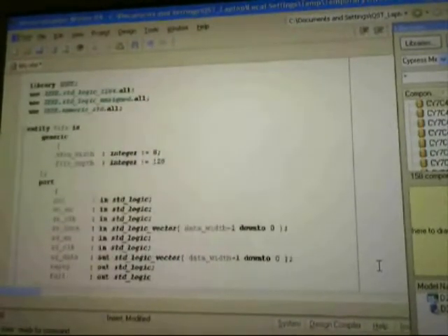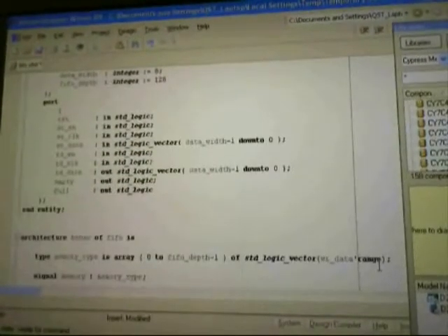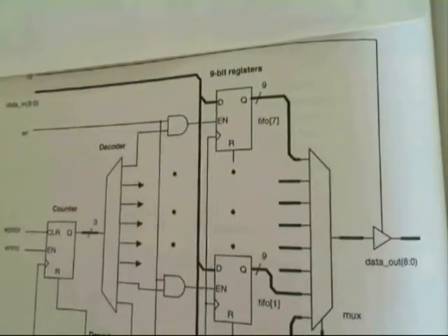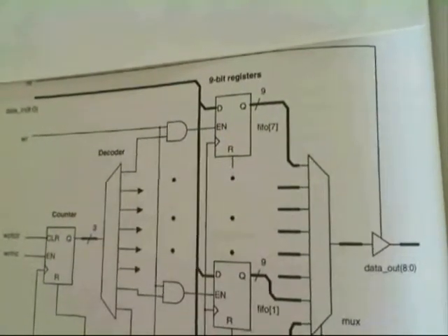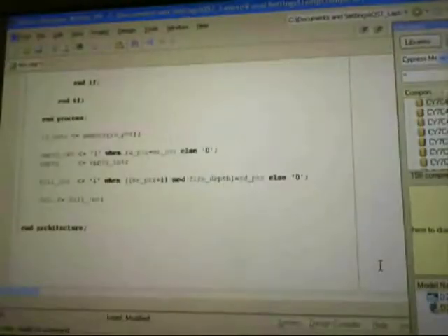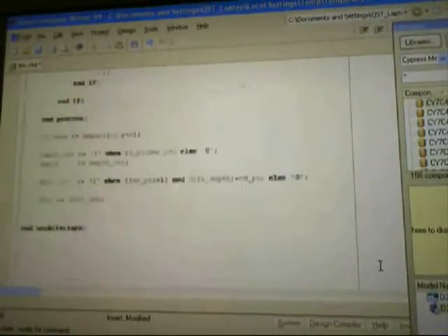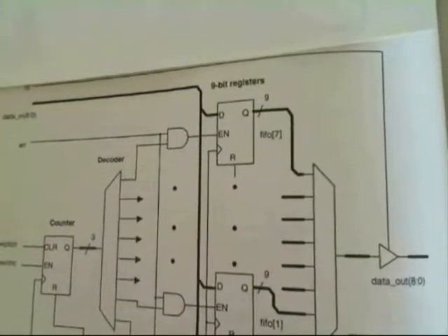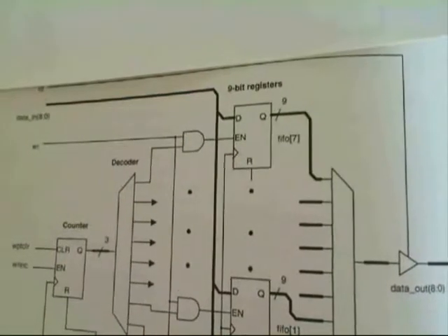It supports FIFO data bits from 1 to 1024 bits, supports independent clock domains. Our sophisticated FIFOs also support error correction, support for packet mode, and support asymmetric ratios, read-to-write port ratios.